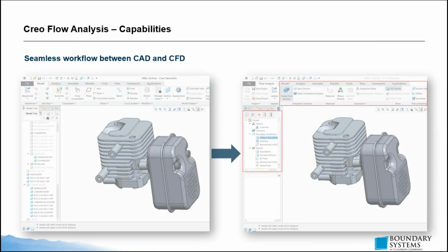All right. So Creo Flow Analysis is the solution for that. Creo Flow Analysis is software that was embedded into Creo sometime, I want to say, around Creo 5, and the functionality has been added to Creo 6 and also been ported back down to Creo 4 as well. And it's basically the ability to run full-fledged CFD analyses right inside of the Creo interface, right? You don't have to export this to another software package. You don't have to create STLs or STEP files or IGES files or things like that.